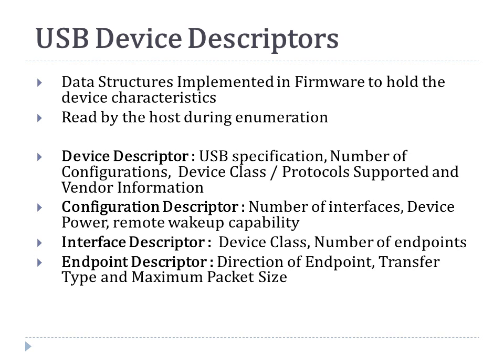The next class of descriptor is configuration descriptor, which tells us about the different capabilities of the device and the different functions the device supports, and then for each function it gives the number of endpoints, and then the endpoint descriptor describes the different kinds or direction of the endpoints, the maximum transfer size and maximum packet size.